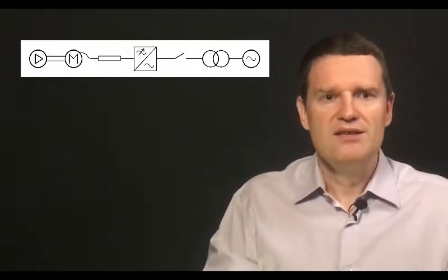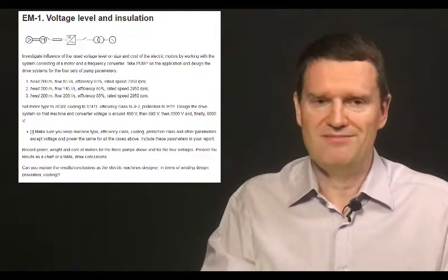The rated speed of the 3 pumps is the same and is just below 3000 RPM. This speed is already high enough to couple some standard motor directly to the pump, so there is no need for any gearbox. So I would propose to design all the 12 systems using the same topology, the one with a step-down transformer. By the way, it is shown in the exercise description.